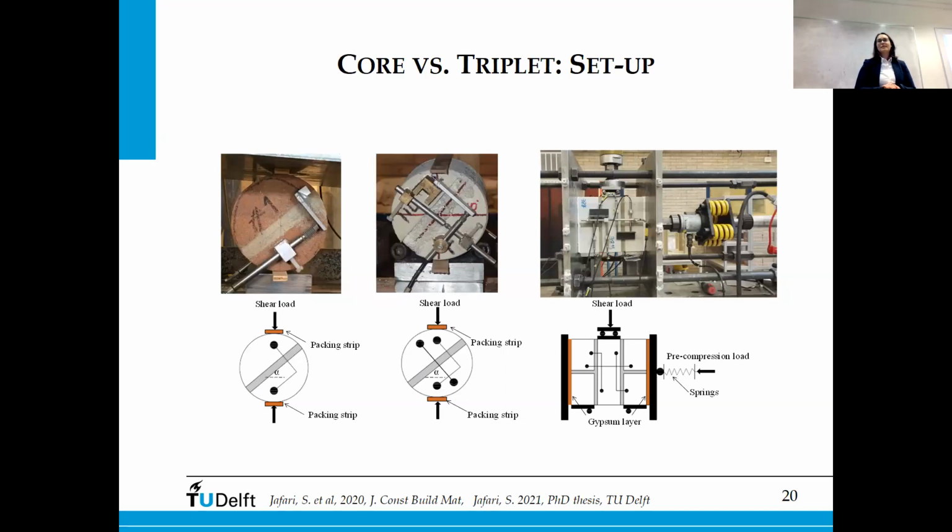Okay, the fundamental question here, which I'm sure needs much more discussion than what we have here: why would you go for homogenization when you can almost predetermine the crack propagation in masonry and just use a discretization of the model on each side of the crack?